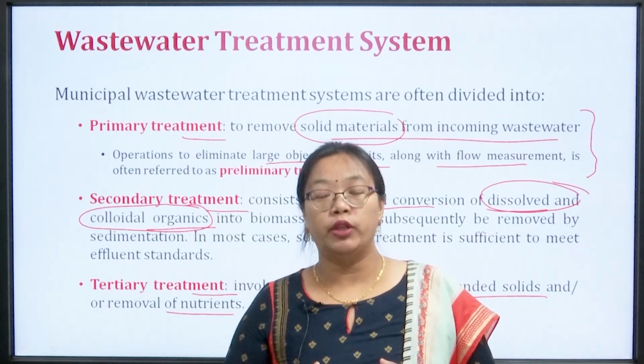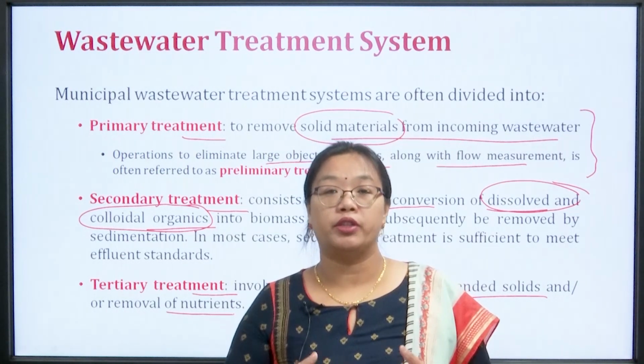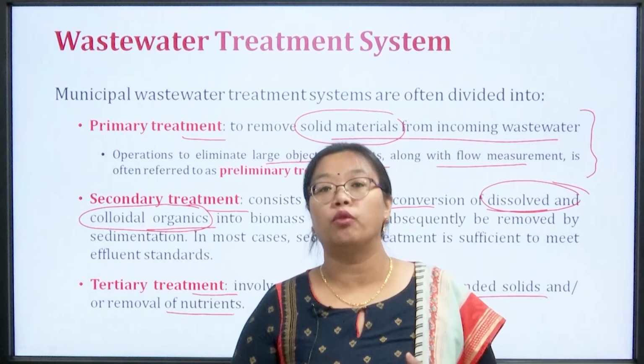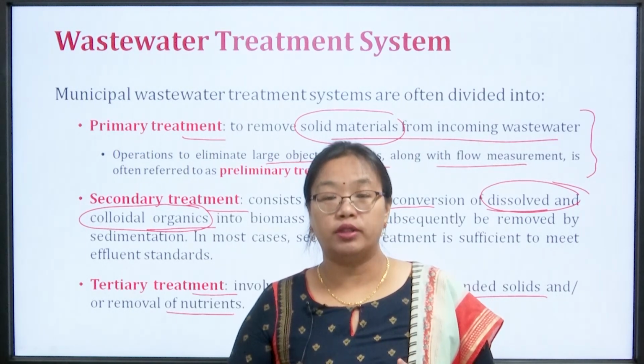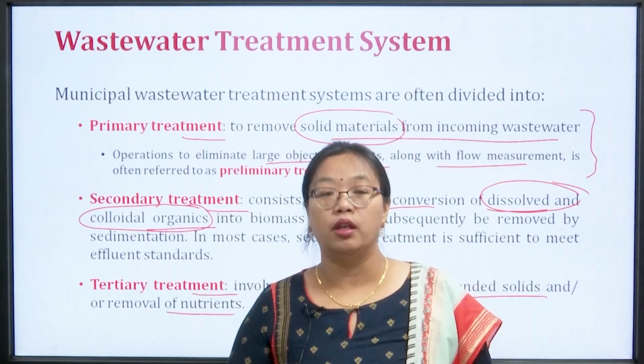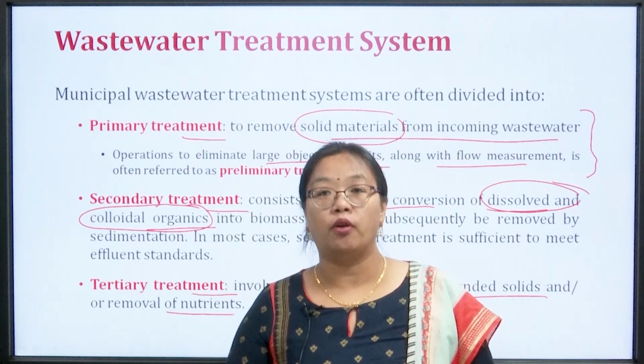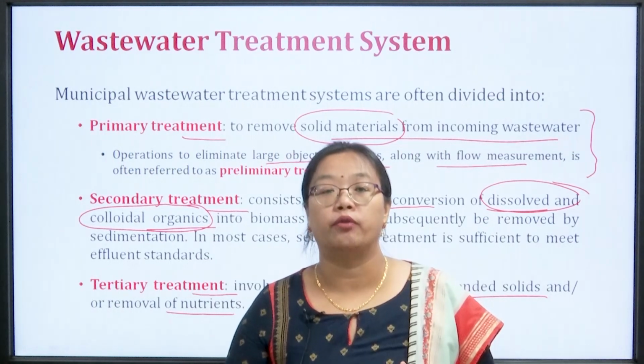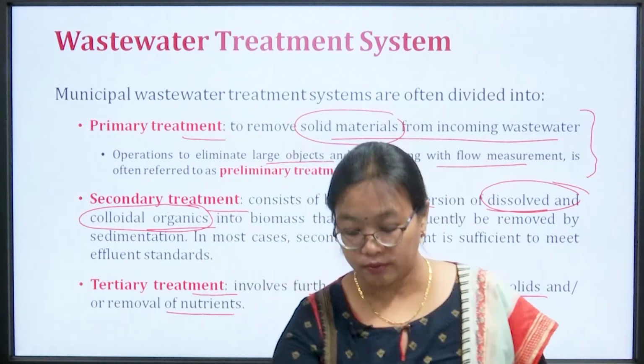When you talk about a water treatment system, tertiary treatment is the most important, like you go for chlorination, which is most important. But here tertiary treatment is the least important, and you generally go for it only when certain conditions are required for the effluent standards.